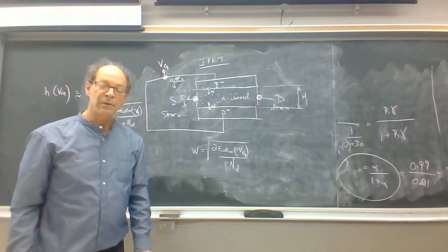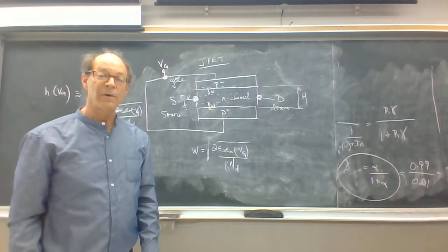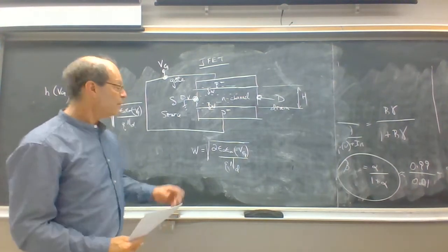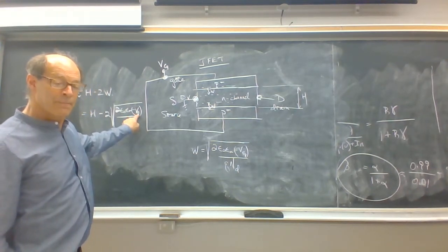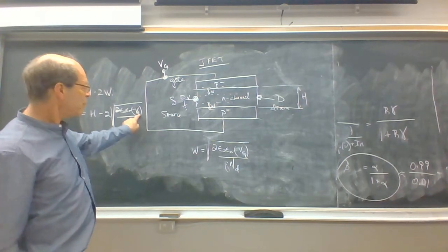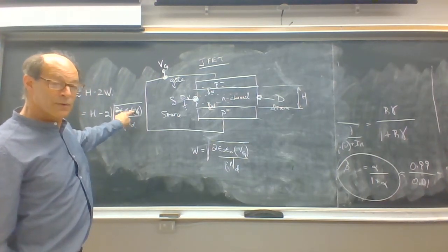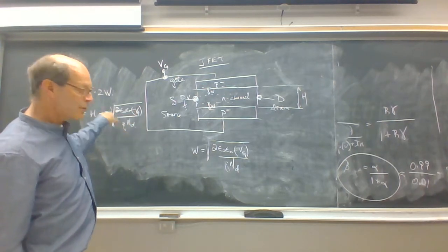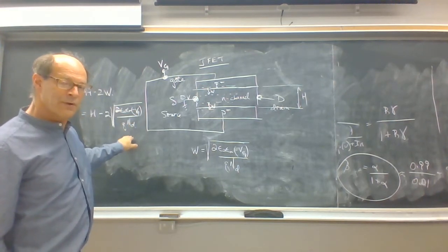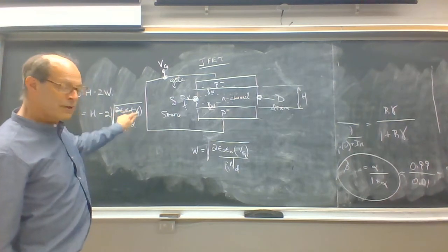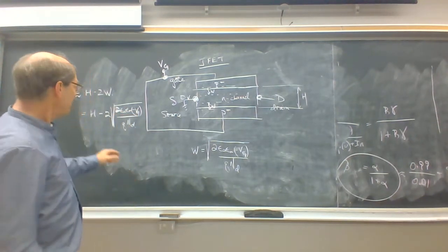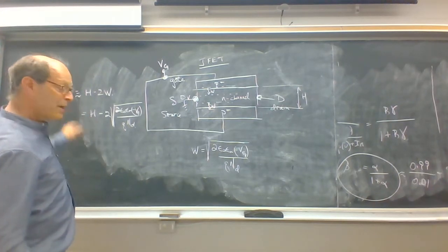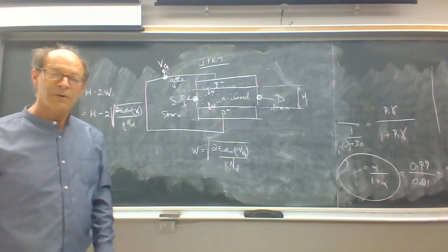Now, something interesting happens, because if you continue to make the negative voltage minus VG larger and larger, of course, the minus sign makes this a positive number because you can't take the square root of a negative number. So VG is negative, minus VG is a positive number. As you make that number larger and larger, eventually the channel thickness will approach 0.